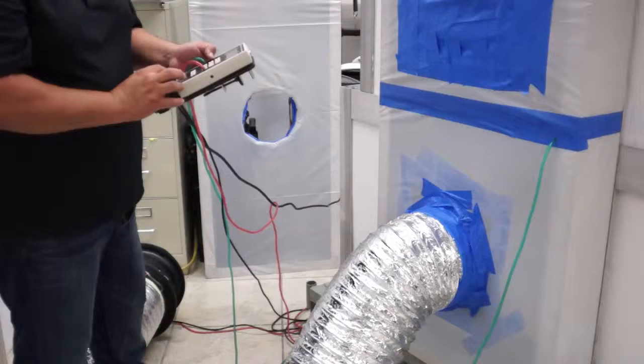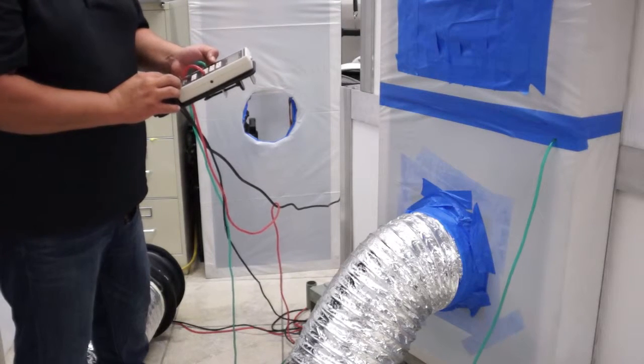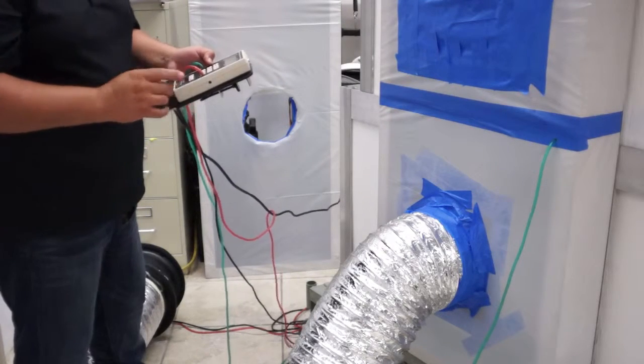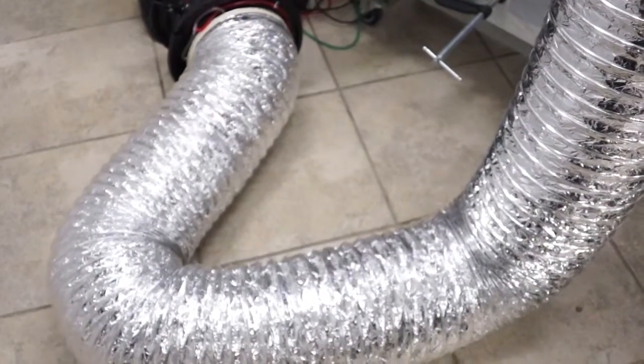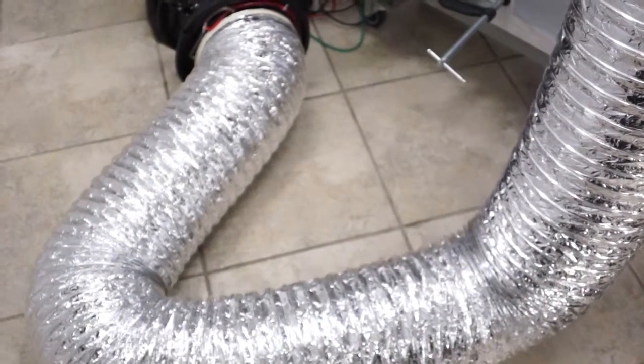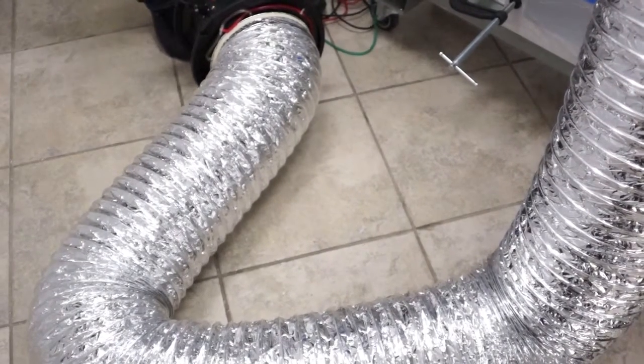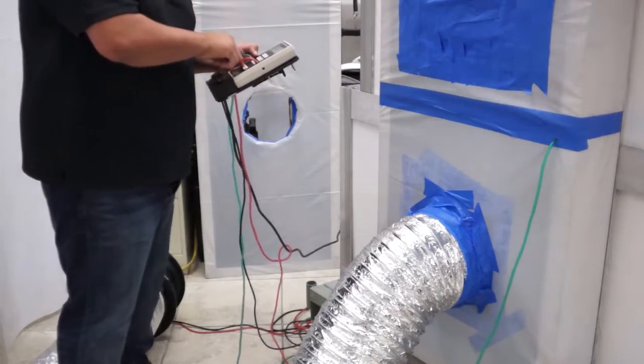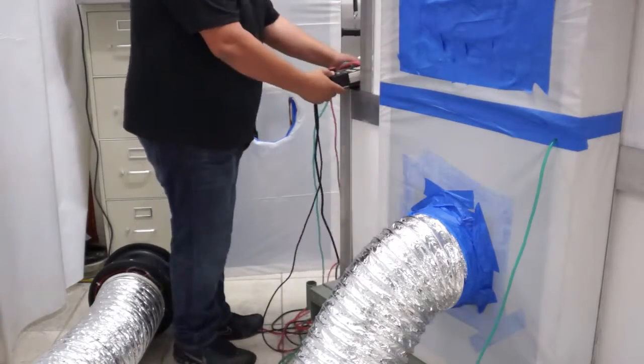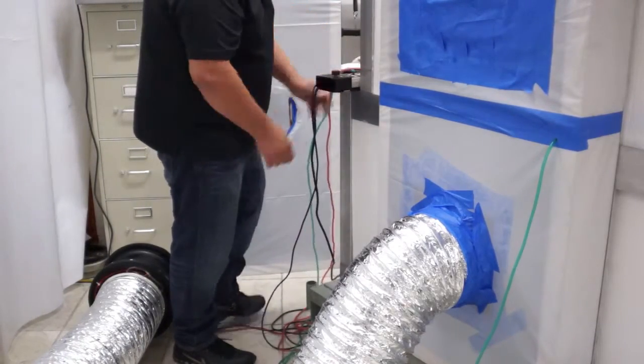We will set the pressure gauge for the same pressure we used on the upper chamber and turn it on. You can see again the ductwork is expanding as more airflow is passing through. The difference is an extra 300 CFM passing through the bottom window into the interior of the room. This airflow was blocked by the backup window on the first test.